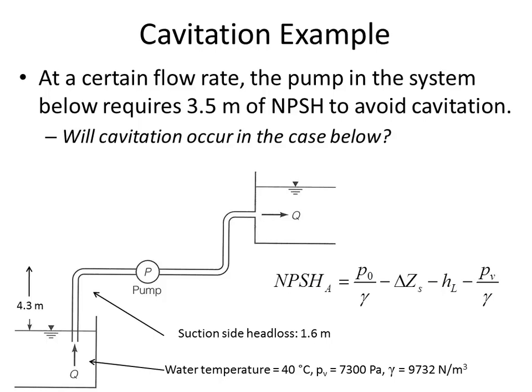And from an energy standpoint, if you're just looking at the energy equation, flow from 1 to 2, the energy equation is sort of blind to that. The location of the pump being here versus there isn't going to change the friction losses. It's not going to change the local losses. The velocity wouldn't be any different. It's just really a matter of avoiding cavitation.